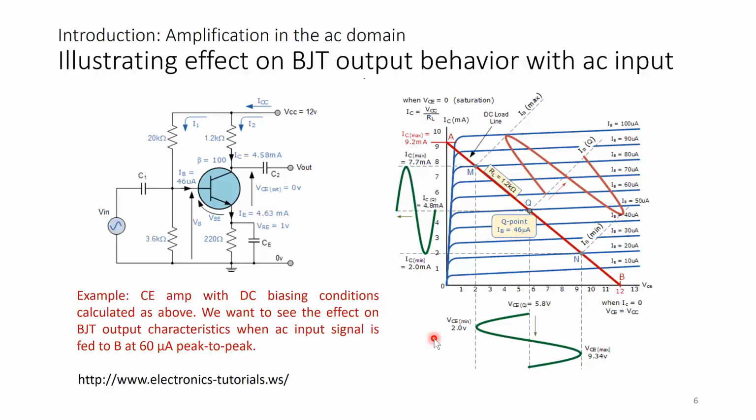Now, before we leave this slide, I'd like to also point out that if we incorrectly design our amplifier circuit and set the biasing Q point at the wrong position on the load line, or we apply too large an input signal to the amplifier, the resultant output signal may not be an exact reproduction of the original input signal waveform. In other words, if the amplifier leaves the active region, it will suffer from what is commonly called amplifier distortion. So the next slide is an example of amplitude distortion.